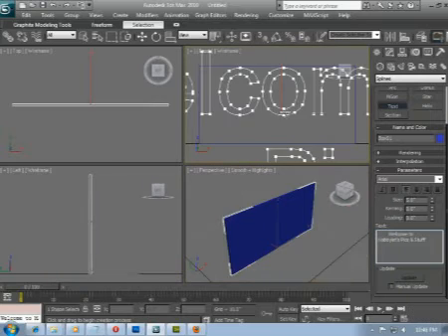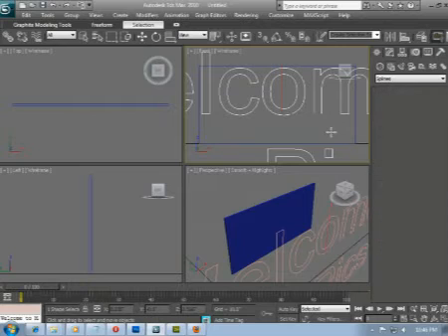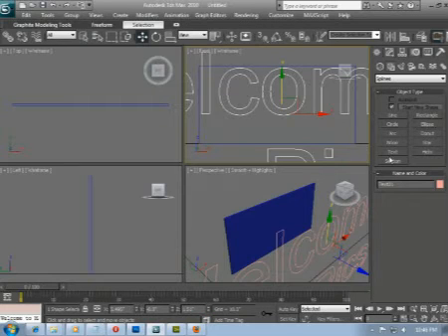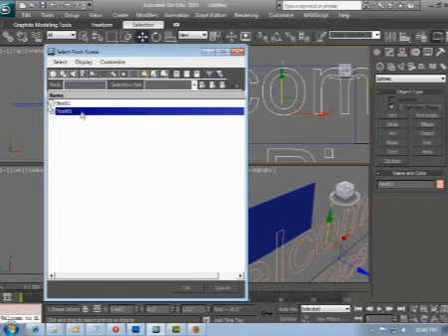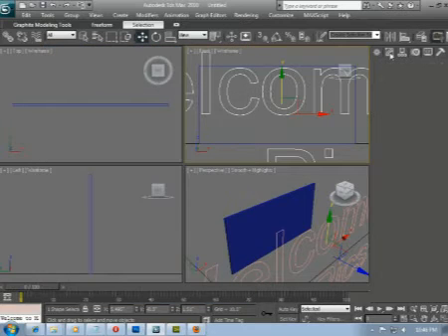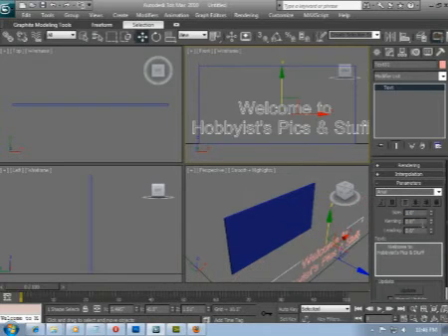And if we click in the front view, oh, way too big. But let's right-click in the front view again anyway to turn off that text button, so we don't create a whole bunch of text objects. Then to select text again, we can hit H. It was auto-named Text1, highlight, and OK. Now that it's selected, let's go to the Modify tab and set the size to 1. Closer. But this is probably a good time to add the light and camera.